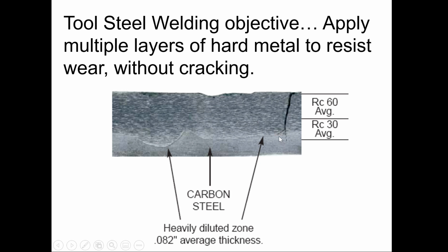You have to know your filler metal is one of the other points. You have to know the filler metal you use and what you've been using to achieve a certain thing. Some materials you just cannot put 3 layers on or it will start to crack. And there are tool steel filler materials that are made to crack. We have lots of them, and they use a lot of these even in places like drilling heads and all kinds of things, where the tool steel surface will crack, and that's normal. It's just that hard and that wear hard that we have to consider for it.